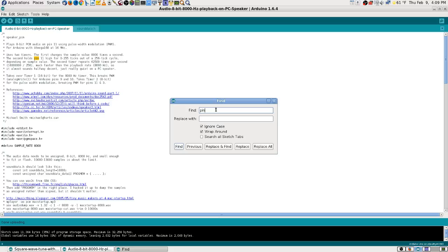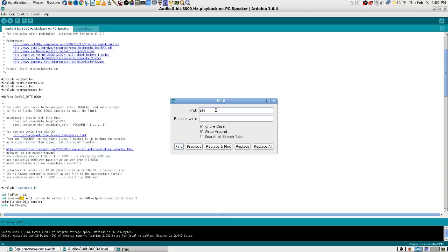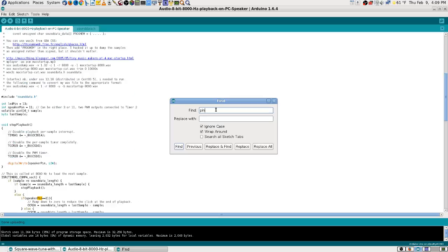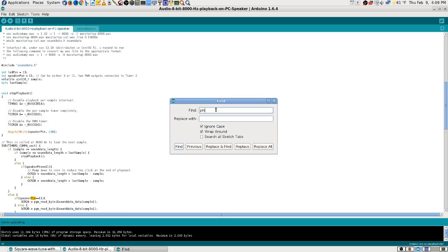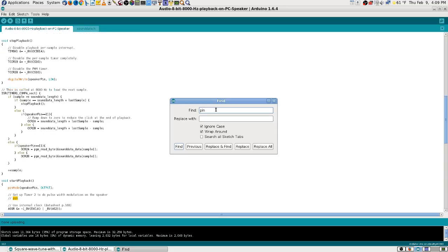I think I'll try pin 3 though. But I don't know about this pin 9 and 10 business. I mean, I wouldn't be scared to try those because I've already used pin 9 and 10 before. LED pin is 13, but I would have been very wrong if I'd moved my ground to LED pin 13. I might have burned up my Arduino, so I'm glad. Pay attention, kiddies. When you're a new kiddie like me, you better pay attention.